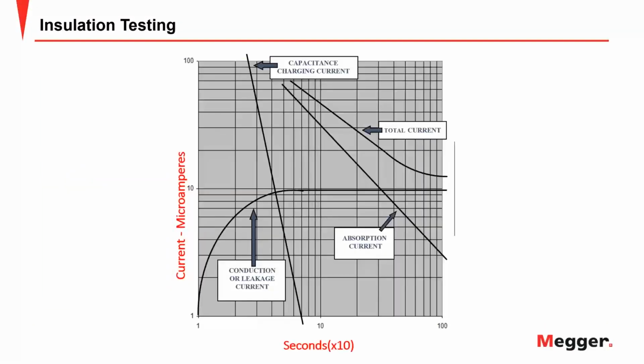So this is what they do. Your capacitive charging current is in the capacitance of the test item, and it's in the design. It doesn't vary appreciably, and there's nothing you need to worry about. But a big motor winding, for instance, has a lot of capacitance, and so that will charge up at the beginning of your test.